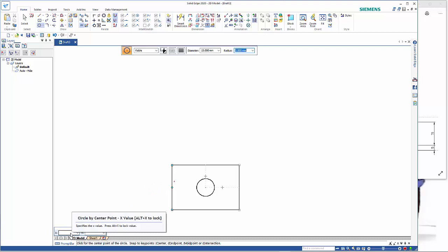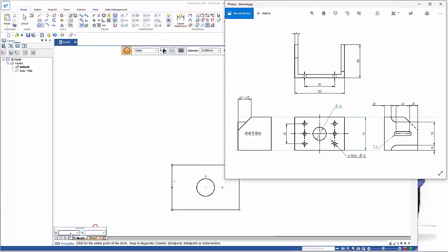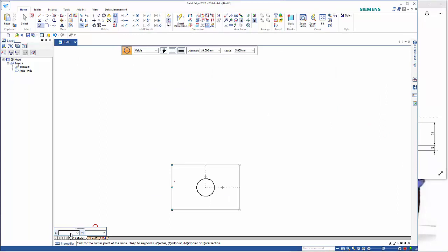If you hover over here, you can see that you can use Alt X to move yourself into that X box. So we're looking at 90, so it's 30 in from the left hand edge and 20 down. I can click in here and go 30, tab across, go 20, and you can see that it's giving me that position. From here I can hit the escape key,